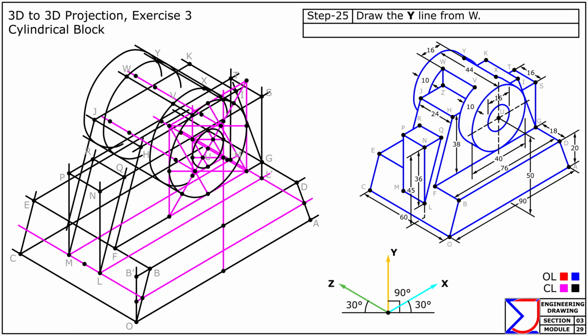At point W, draw remaining parallel line. The intersection obtained is point Z. At point Z, draw remaining parallel line. Alright, with all the construction lines completed, the solid block has taken shape. Carefully darken only the visible edges to finalize the isometric view.